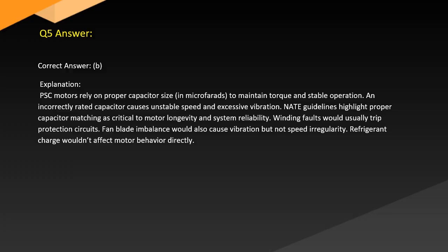Winding faults would usually trip protection circuits. Fan blade imbalance would also cause vibration, but not irregularity. Refrigerant charge wouldn't affect motor behavior directly.